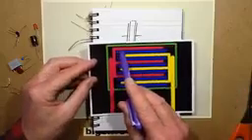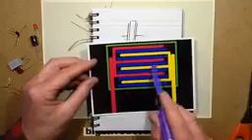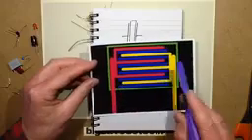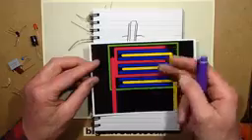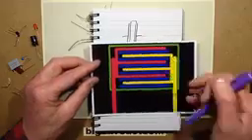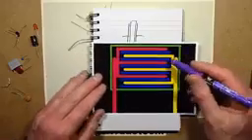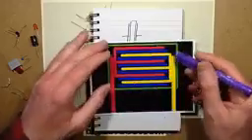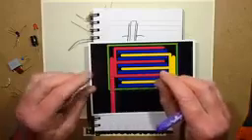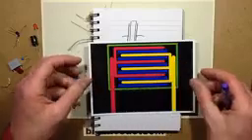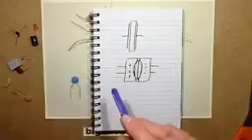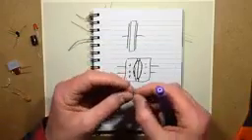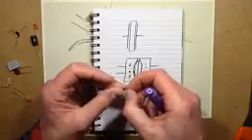And if you can imagine that the blue is layers of insulation in the ceramic capacitors, and these are metallized plates, then by alternating the poles, creating a comb of them with insulators, and then putting a metallization down the end to connect them all together, you can create quite a large capacitance in a small area just by making it a multi-story capacitor, so to speak. And the layers of insulation in these are still going to be super thin. You'd need a microscope probably to see all the layers.